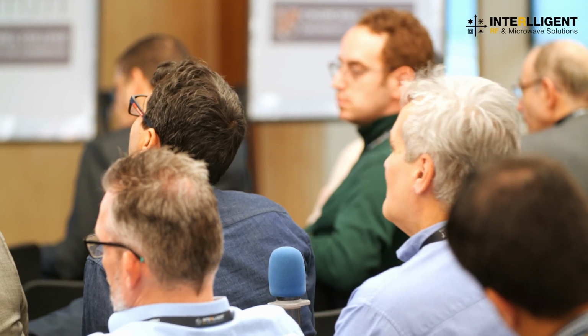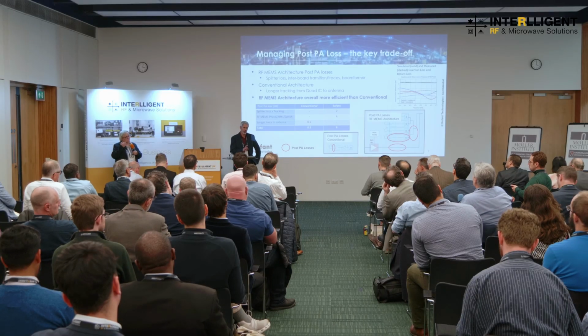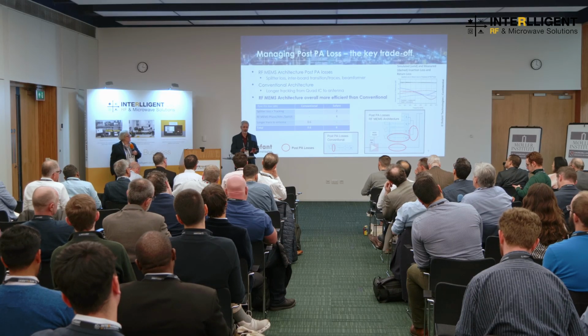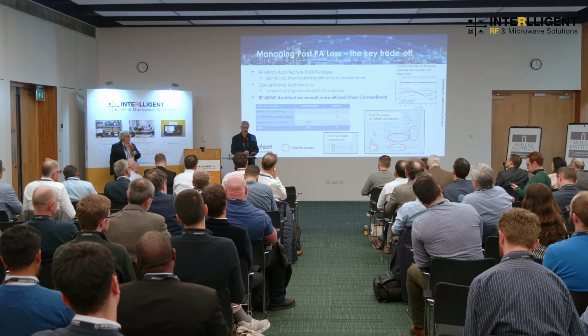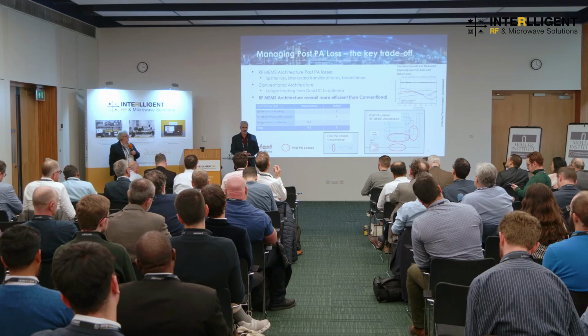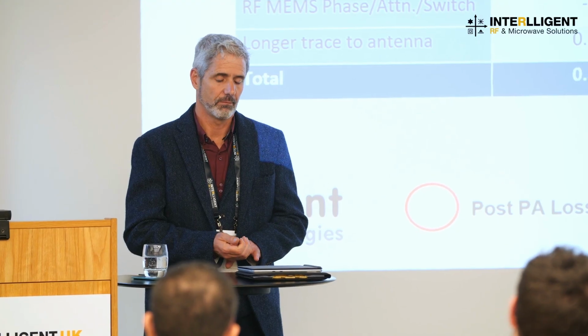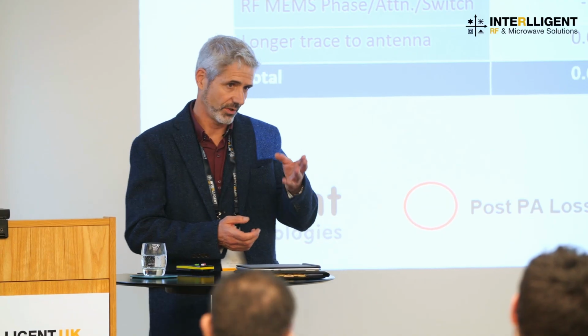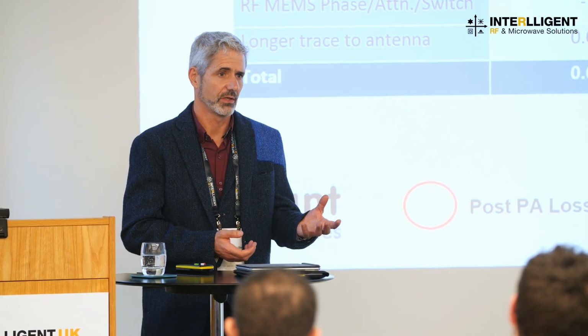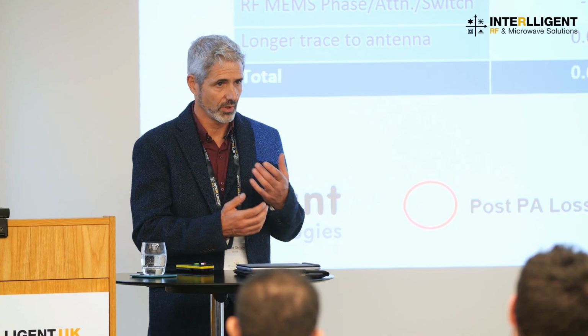Yeah, I didn't talk about the receive side because we're very pragmatic. We don't use MEMS on receive, and we do something different on receive than most other people do. Because you want the LNA close to the antenna element. For the same reason that we want on transmit, we want it right beside the antenna element.